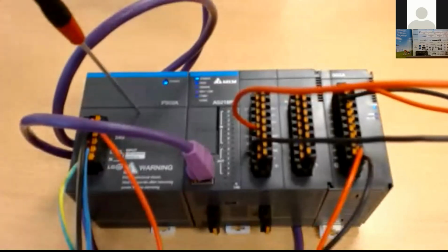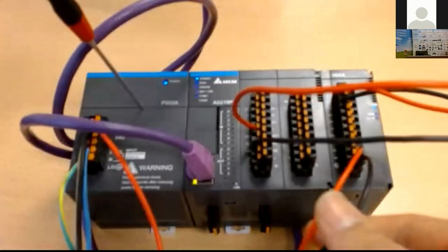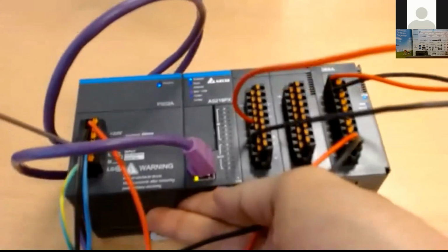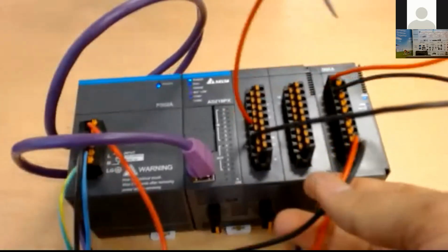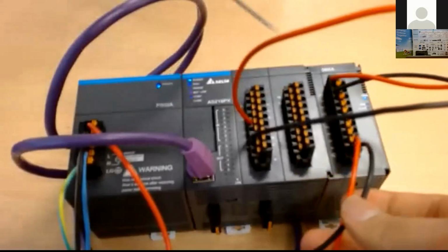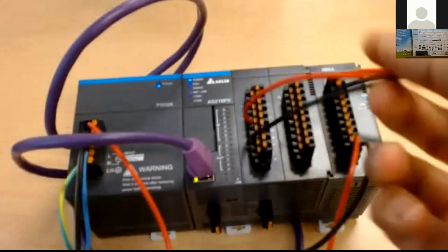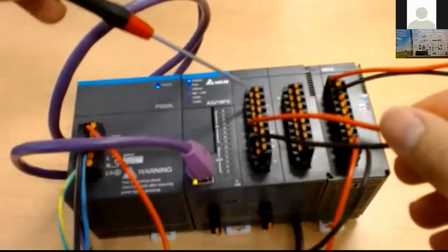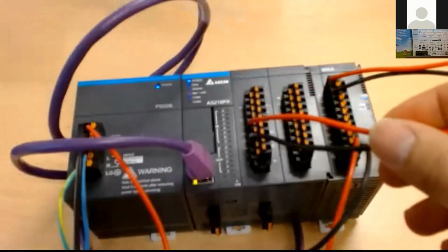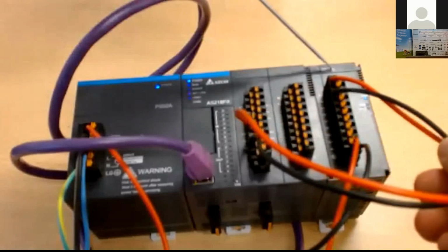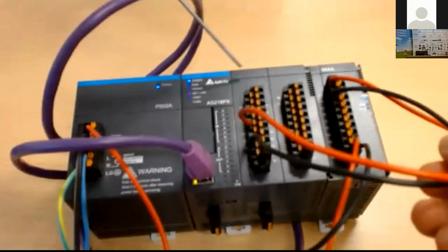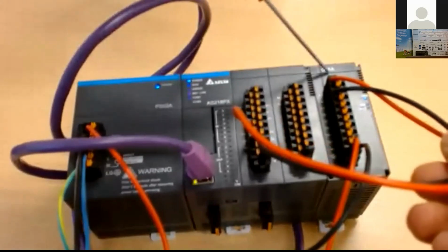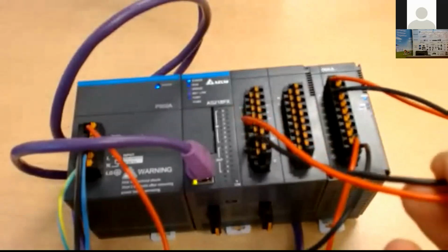One of you asked me whether the power supply is mandatory. No, it is not mandatory, but as you see, there are some functionalities like this. So I can get an additional 24 volt over here to supply the module itself. Right now, I don't have any analog source. So what I do is use the built-in analog I/O as a voltage output, and I will use the module as an analog input. I will generate from the CPU, and I will read from the analog module input. This is what I have as a setup.